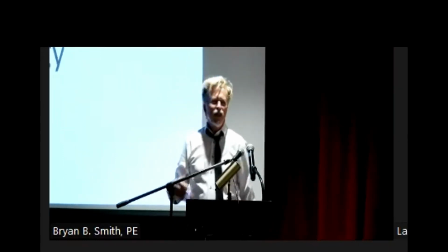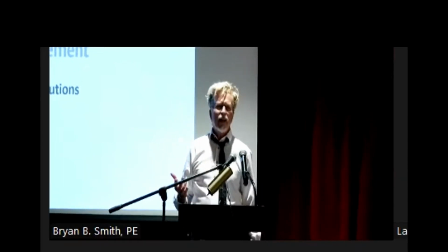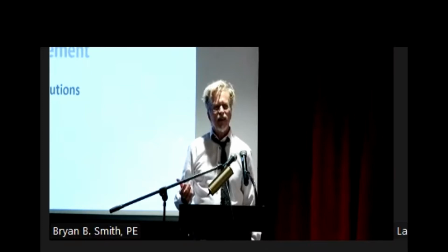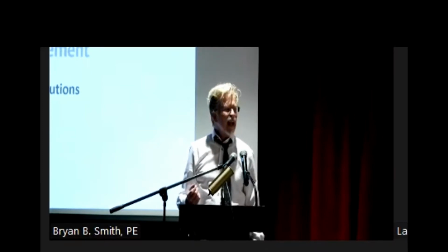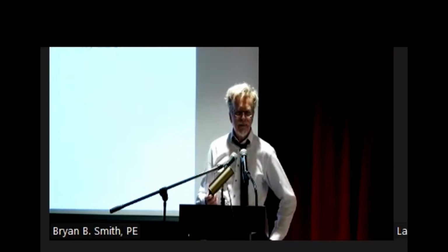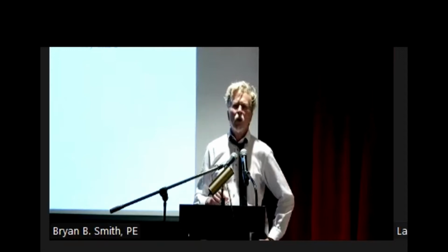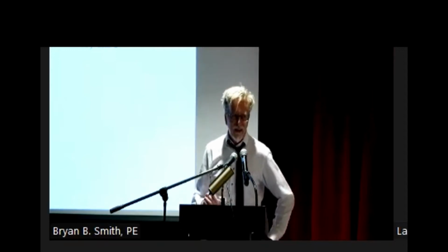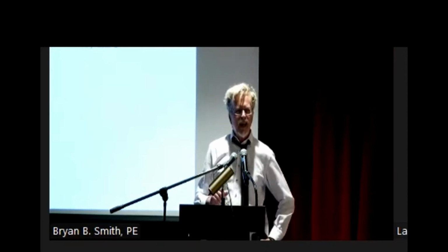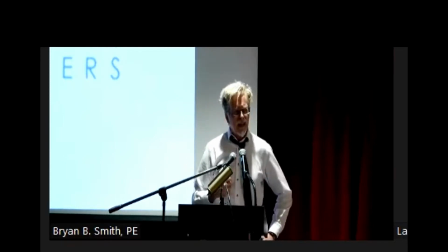But let's talk about gravitational acceleration. Is it the weight of the body or the distance it's traveled? So is that weight actually doing anything to increase our closing time of our valve? No. Okay. So we're like, ooh, spring, right? Let's put a spring on our check valve to exert its own mechanical force to pull the valve closed faster.